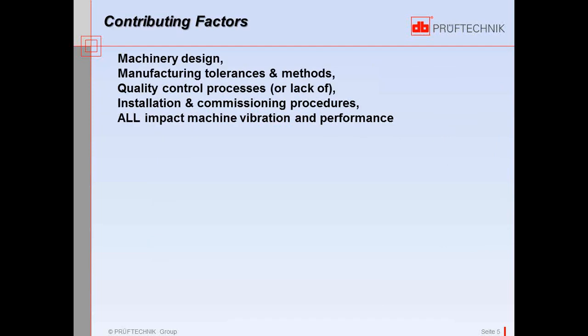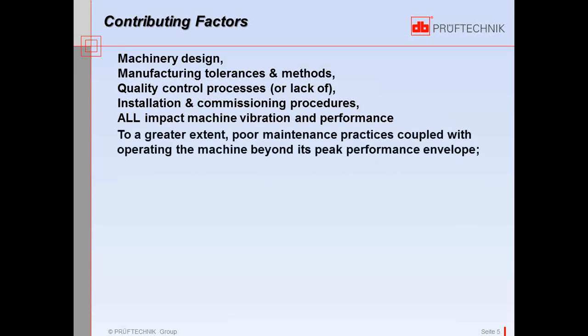Machinery vibration, there are other contributing factors to that. The basic design of the machine is a factor. Any of the manufacturing tolerances and methods used to manufacture and produce the piece of equipment, the quality control processes or lack thereof that the manufacturer has implemented, installation and commissioning procedures, all of these are factors which will impact machinery vibration and performance. But to a greater extent, the practice of poor maintenance coupled with operating the machine beyond